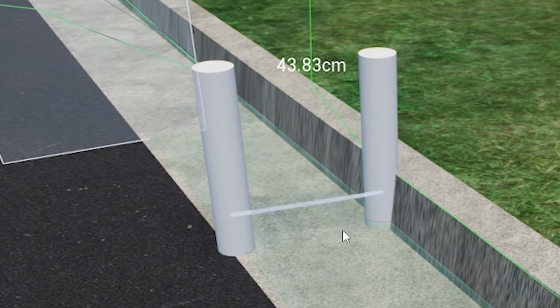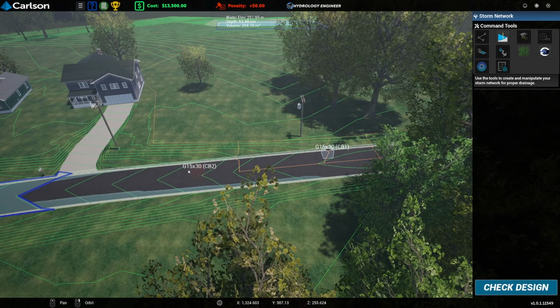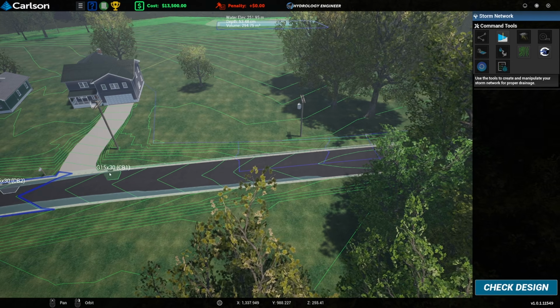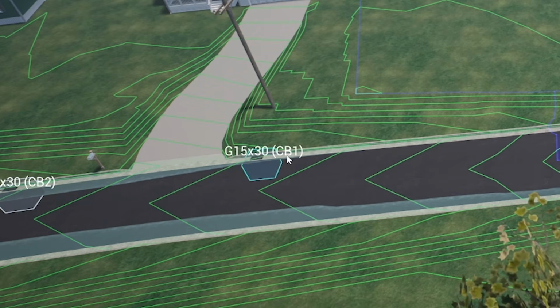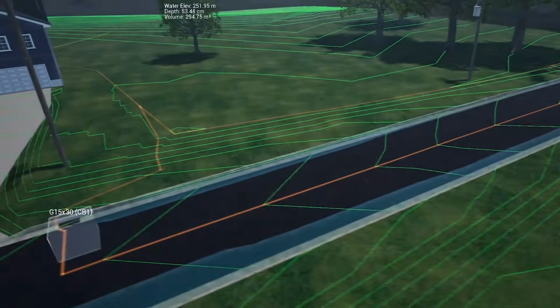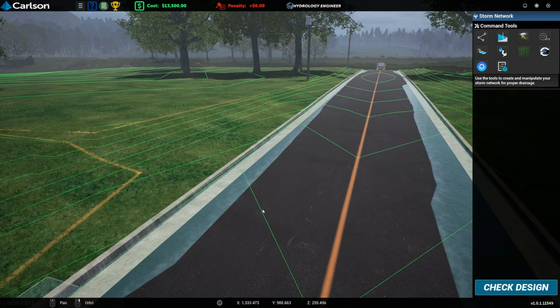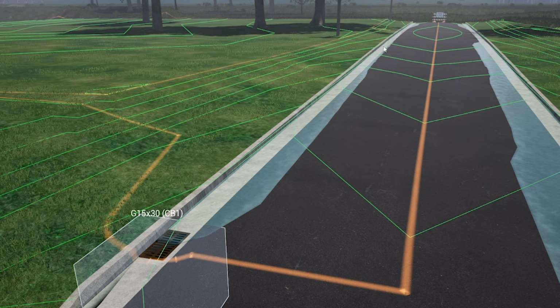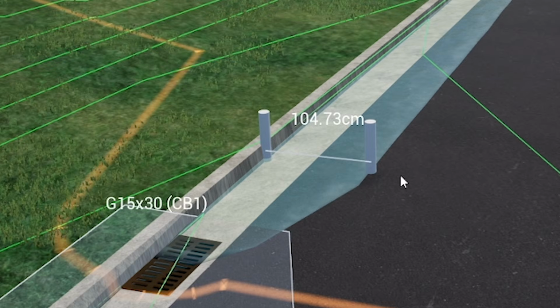So we can add another 2 meters on. So basically I can take this gully and probably move it all the way down there, and this first one, move that down to, I don't know, over there-ish. And then if we run the storm again, that's the thing with this game, it's more trial and error than real life. In real life, you do all the calcs to work out the flow width as it goes on, and then it will just tell you where the 2.4 appears. So what is that? Oh, that's still only a meter.